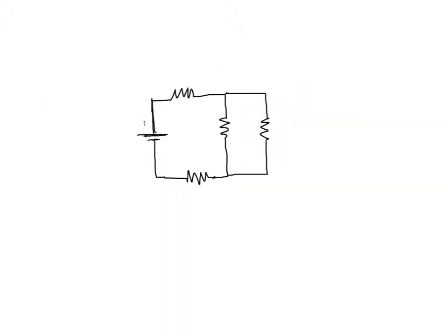Okay, so here's my positive terminal in my battery, here's my negative terminal. I'm going to have current flowing from positive to negative. I'm going to call this amount of current I1. You'll see why I have to designate the currents I1, I2, because as the current passes through this resistor, the current leaving the battery is I1. All that charge has to go through the first resistor.